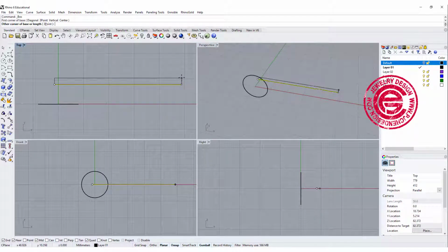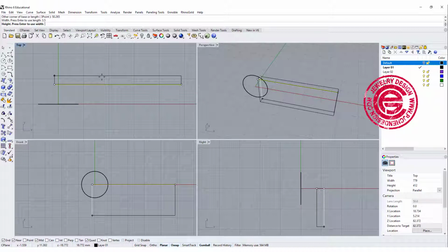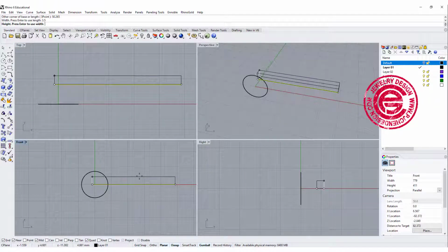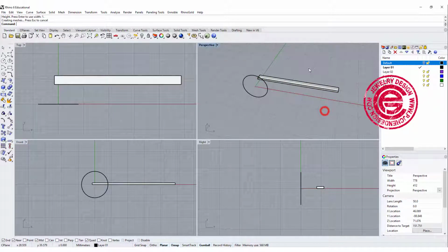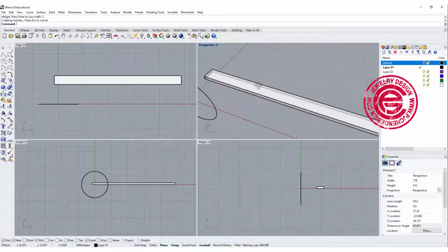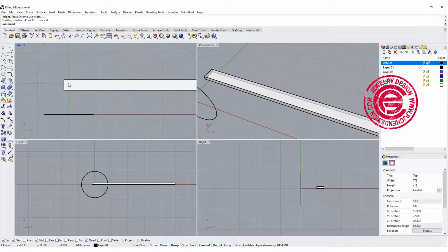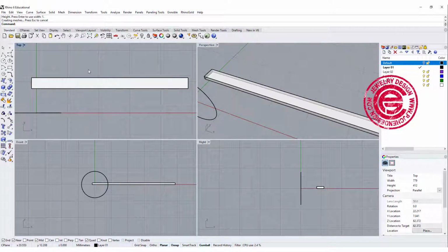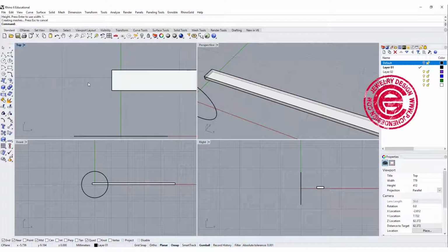For our ring shank, it's going to be the same length, so I'm going to type 50.265, and then the width is 3.5. And for the thickness, I think this is not too thick of a ring, so either 1 or 1.2 will work. So I'm just gonna type 1 there. So this is the ring shank that we are going to have. We're gonna do the fitting later, but let's go ahead and do the buckle part. On the buckle part, I'm just gonna do it right here.